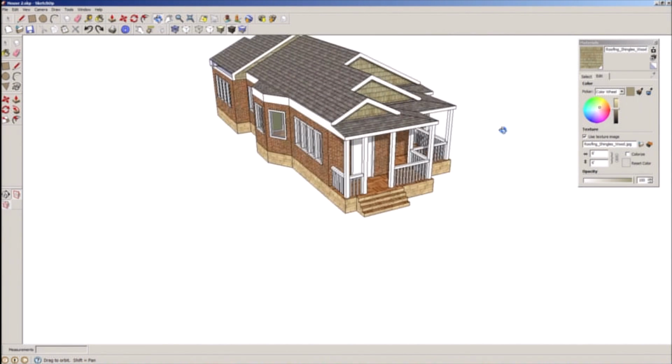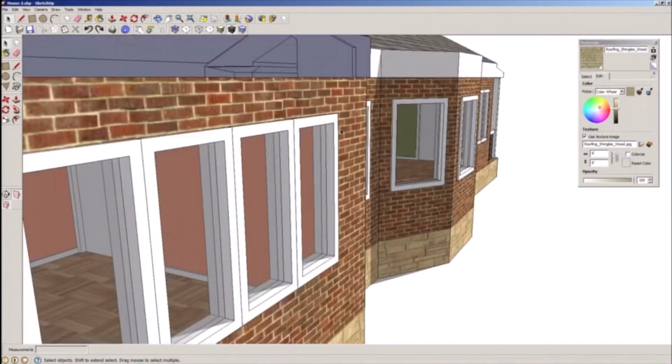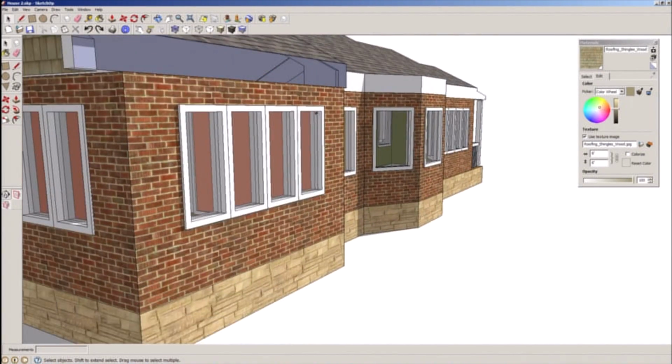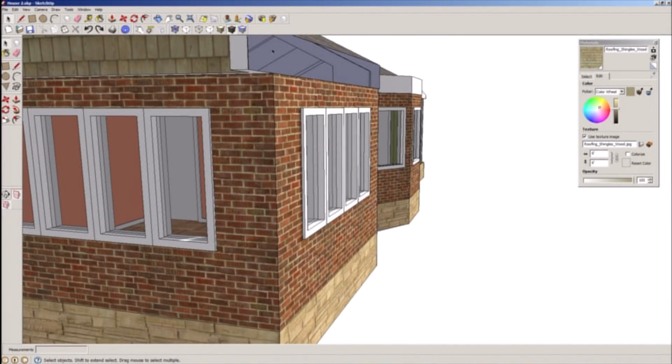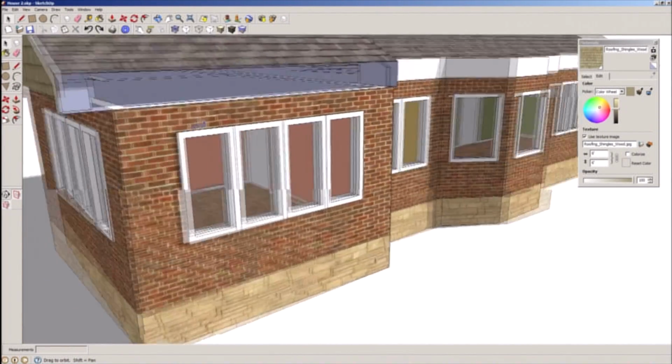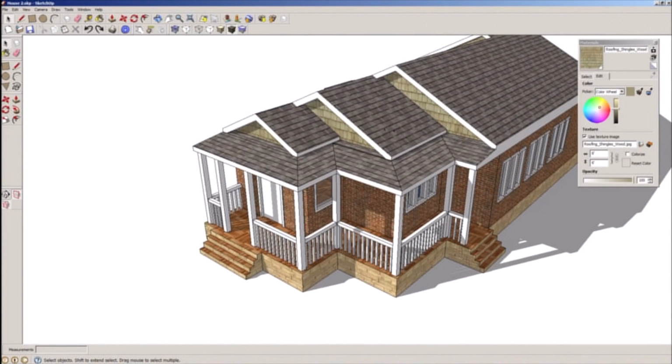In SketchUp, the front and back face are used pretty interchangeably, and you can see I've poked a hole into the back here, and you can see how you can actually get in there, and the back faces are all exposed. So if you have parts of the model that do not have that default texture, it's very hard to spot when you are looking at a back face.